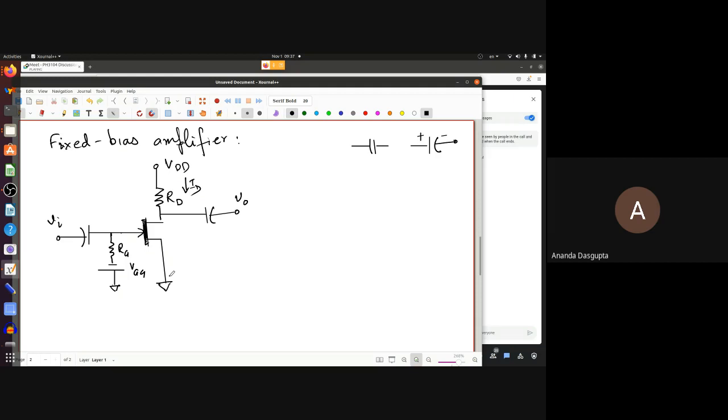So the superposition principle is a standard method which we often use in circuit analysis, but you have to remember that it can be used, strictly speaking, only for linear circuits. So frankly, the only reason you can use the superposition principle here is because you are just using a linearized approximation, which is a very decent approximation, by the way. Just because it's an approximation, you should not necessarily consider it to be a bad thing.